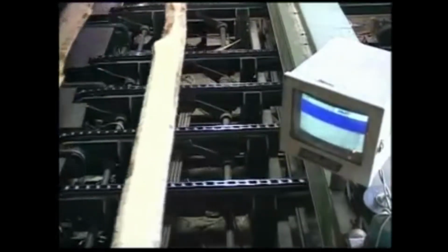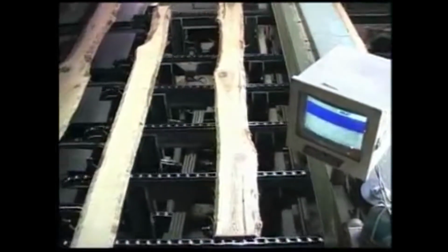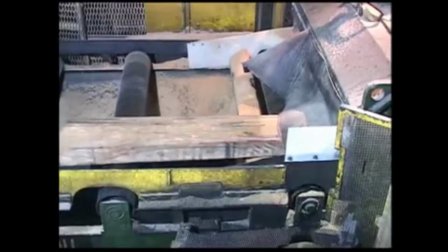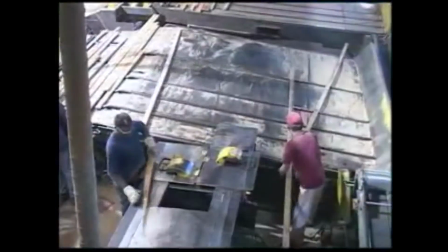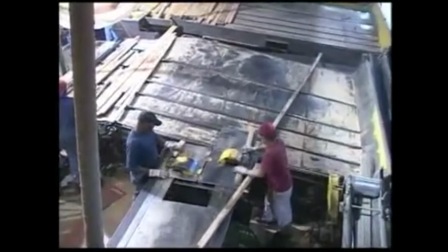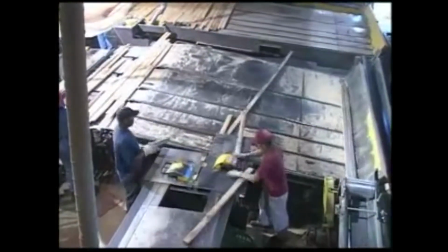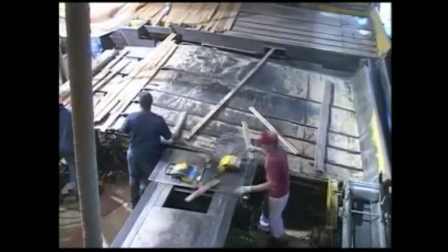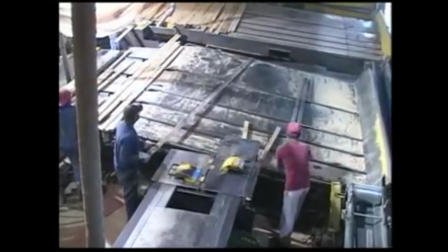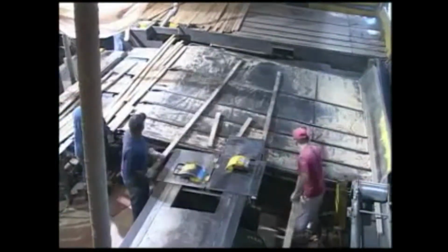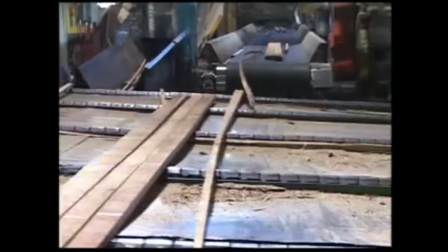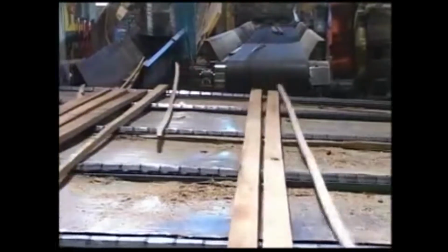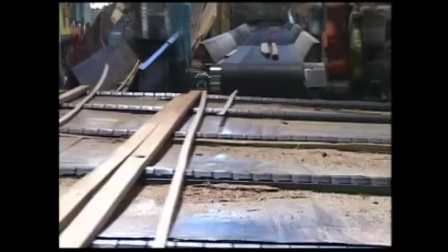The slabs are graded for length, width, and appearance, then cut into rough widths. A 3 1/4 inches wide finished plank would require a 3 1/2 inches wide rough cut board. The slabs are cut into 6-foot lengths or less, cutting out defects, which can include narrow areas, bows, loose knots, cracks, holes, tears, or large blemishes. Wood filler is used to fill voids if possible. On average, these slabs will generate 60% usable product and 40% waste.